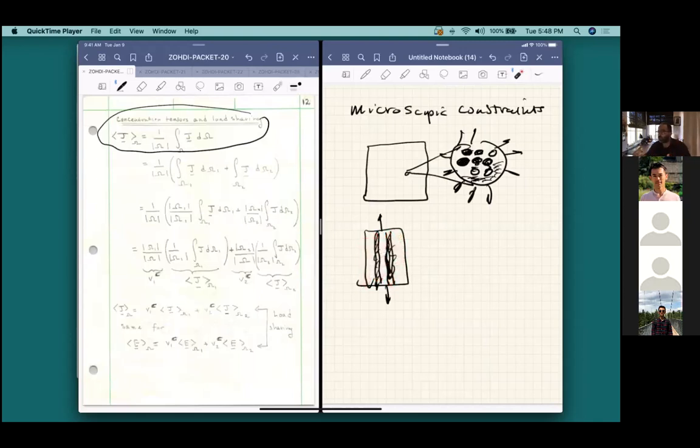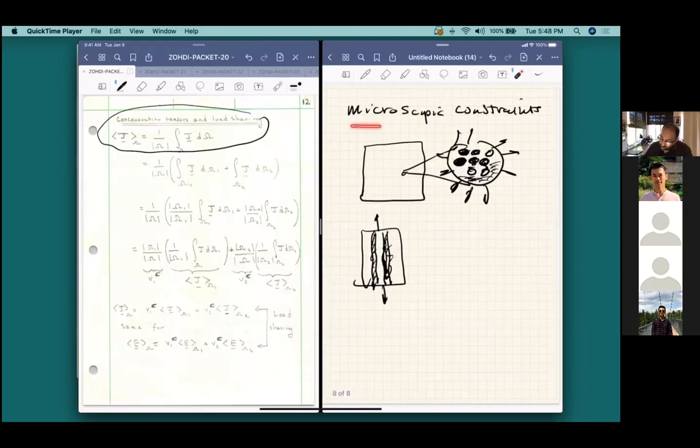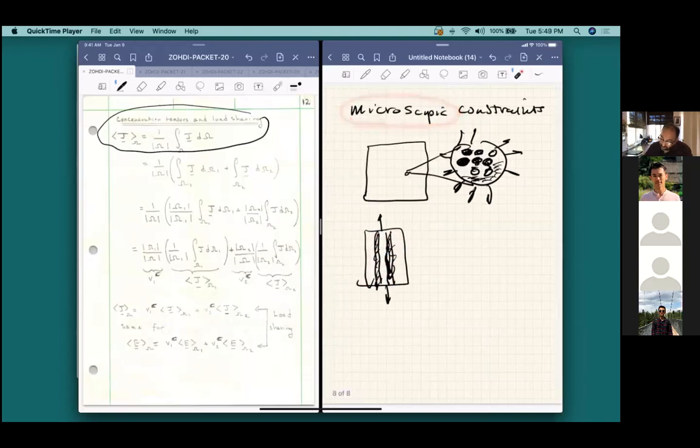And you go through a simple analysis and you find out how much of the load is shared by the steel, how much of the load is shared by the concrete. That's what we do in so-called microscopic designs. We do this in a much more elegant way, and we do this for the electrical fields, the thermal fields, the mechanical fields, and we construct so-called load sharing algorithms or load sharing expressions.